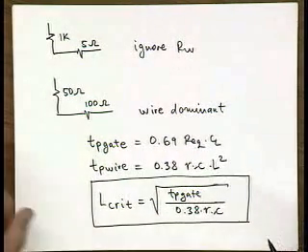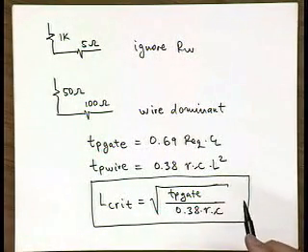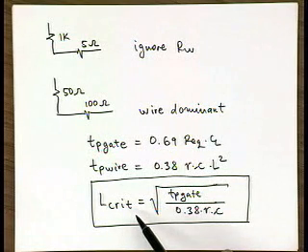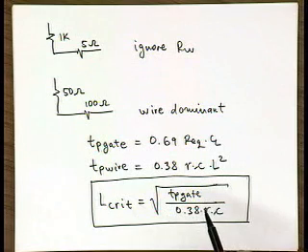What this formula tells you is that if the wire length is greater than this critical length, you really need to include a distributed RC model and take into account all of these wire parasitics. Another parameter you need to consider is the rise time at the input, which is determined by the driving strength of your gate and also what's loading the gate.